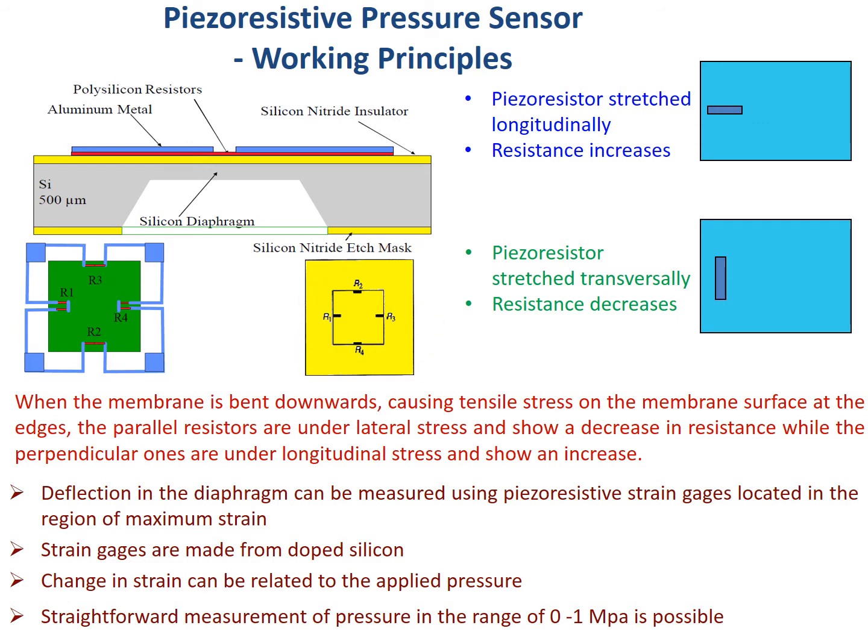So basically those 4 piezoresistors will be acting as the 4 strain gauges, which we will be connecting to the Wheatstone bridge circuit to convert the change in resistance into the change in voltage, right? Isn't it? So now how will these particular things work?